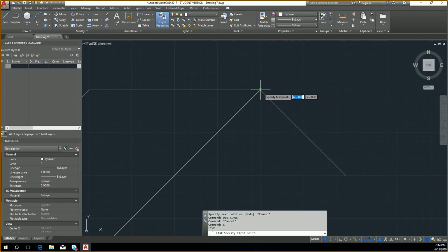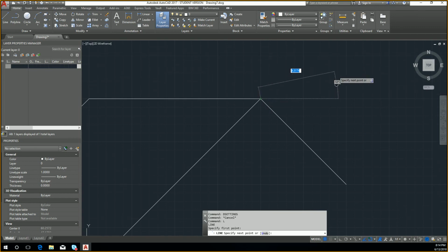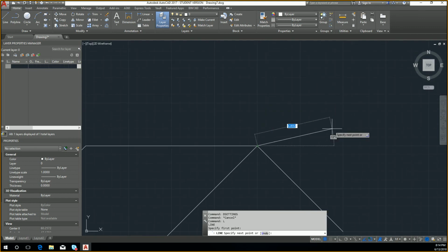There was a good question here, how you can switch X and Y coordinate entries while you're trying to do an absolute entry. So I can turn on my absolute entry by pressing Shift 3 to turn on pound. So let's say I want to go to 10 minus 20. Those of you online can't really see this, but what I'm typing is 10, and I'm pressing the comma key.